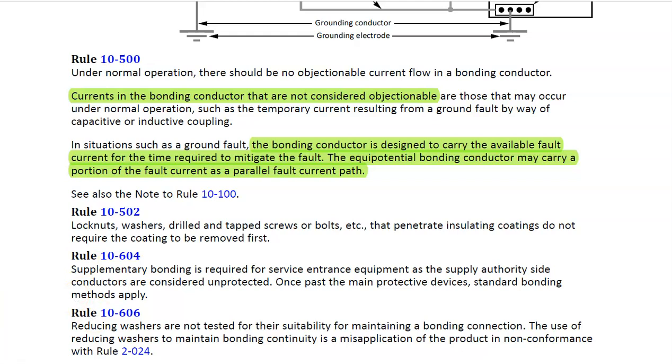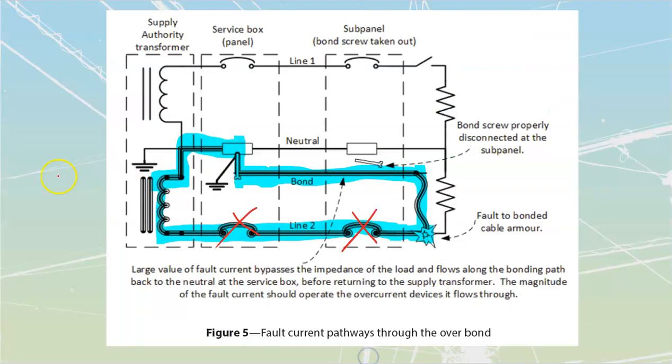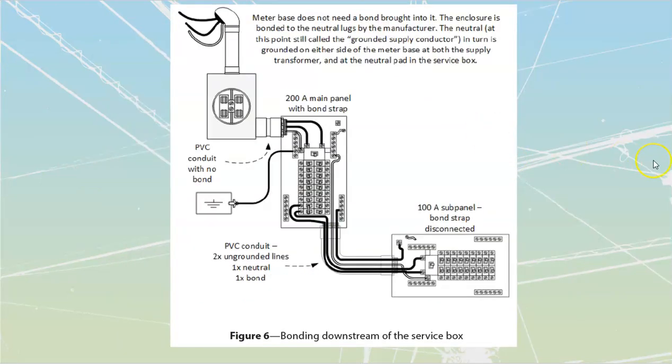All right, going back into this one then. Let's take a look at this drawing over here. Once again, 2015 to 2018, there were changes. One of the big changes was that this drawing over here, these services are no longer allowed to be made. Now, they do exist. You will service installations that have them. You don't have to replace them. If they were installed under the 2015 Canadian Electrical Code, that's fine. They are still allowed to be that. However, going forward, we're not allowed to do it anymore.